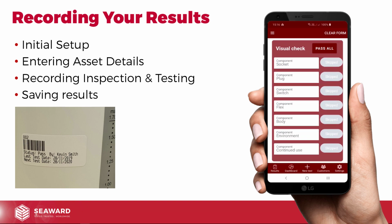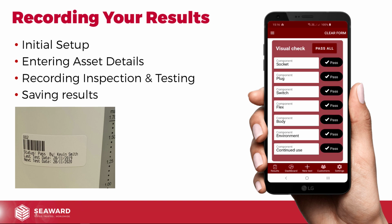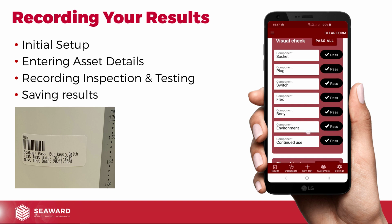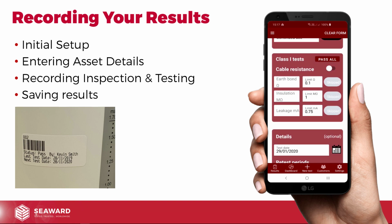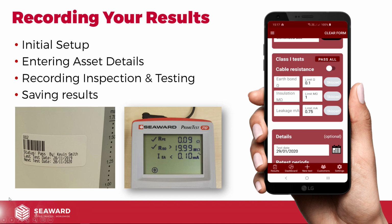That then moves on to the visual inspection screen, so I can either mark these items separately or I can do pass all, to pass all of those items if they're all okay. I then move down to the test part of this. Obviously this is where I'd go over to the tester and perform the test on the tester. So hopefully if I click again, we should see the results that we've achieved from the tester. There we can see the earth continuity, the insulation resistance and the leakage that's come up on the tester.